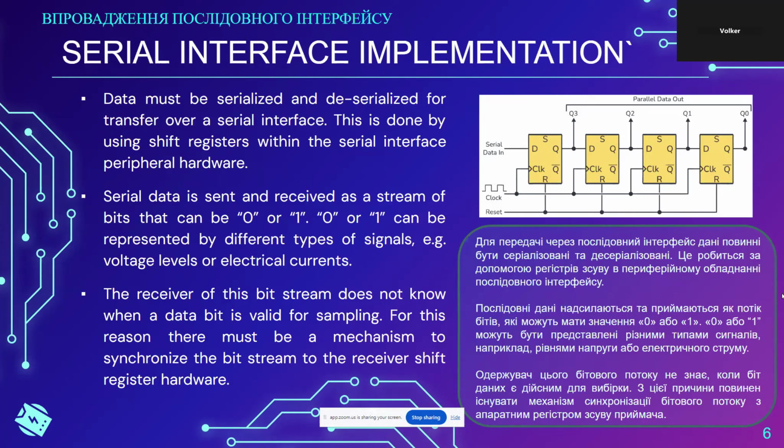I want to point out, for people who want to build a shift register from flip-flops for hobby purposes, for example, or for demonstration purposes, the logic devices that could be used for this are the 74HC74 and the 74HC175.